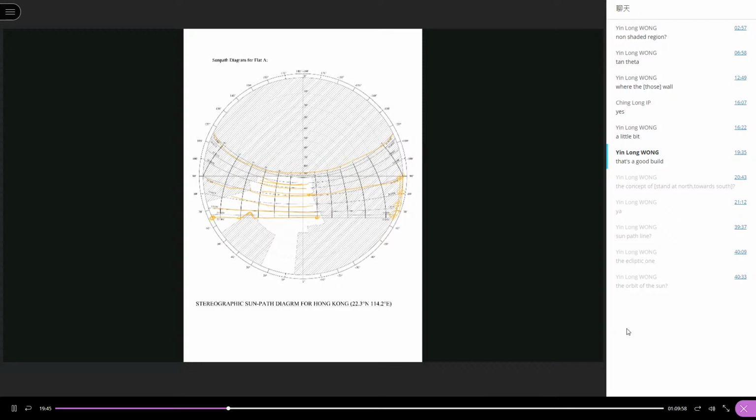If you are interested in the sunlight availability for your home, you can try to briefly plot the external obstruction onto the sun path diagram. You have to know the orientation. Let's say my home is facing southeast.